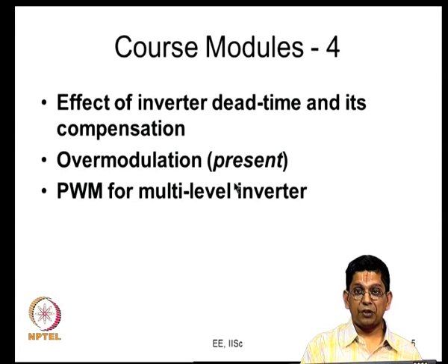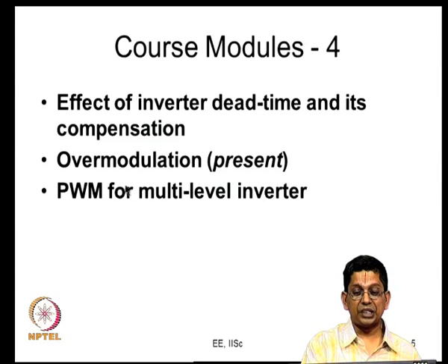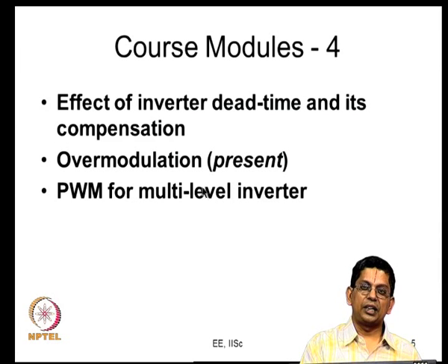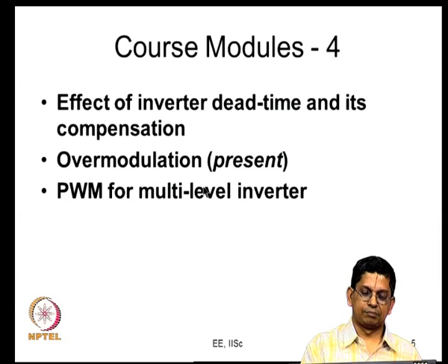So, with the same DC bus voltage and same device rating, you have an inverter whose AC voltage rating is higher. But there is a problem: it introduces low frequency distortion in your output. Therefore, there are going to be low frequency currents, and that is going to lead to several problems. In closed loop control, it is going to be much more difficult to handle. So, these are some things that we will look at now.